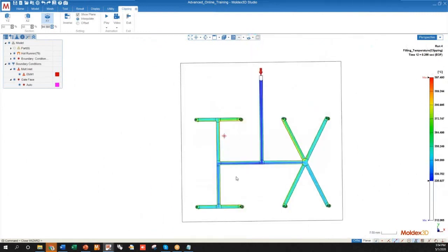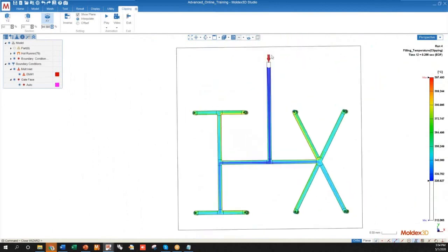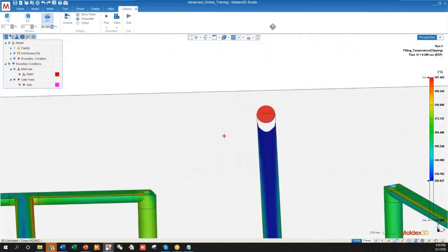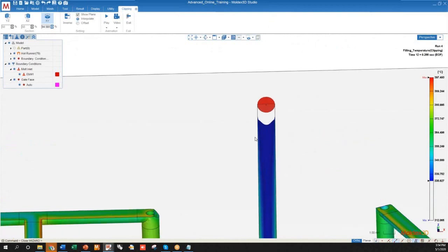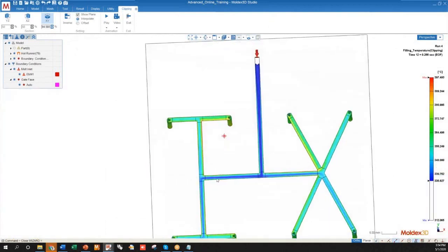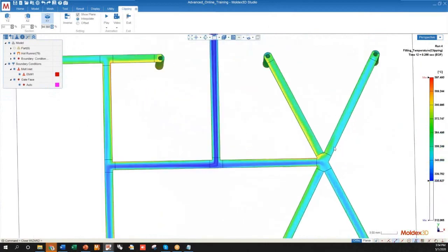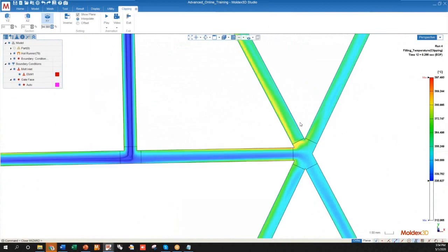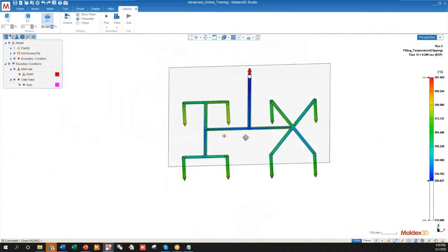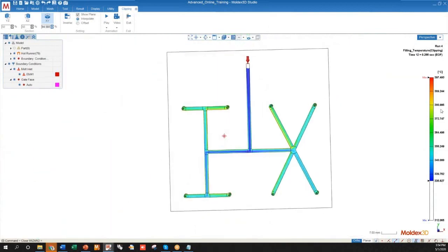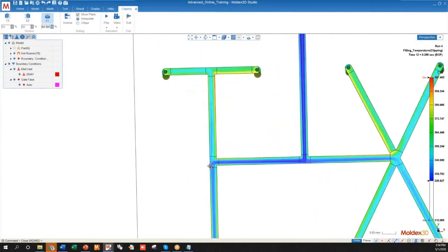And we really get to see a better view, since it removes a lot of what's happening right in the main sprue here. You actually see that the temperature is increasing quite a bit over the flow length. But you can get a better idea of where that high temperature is located by diversifying the color gradient in your result here. So just another way to view it.